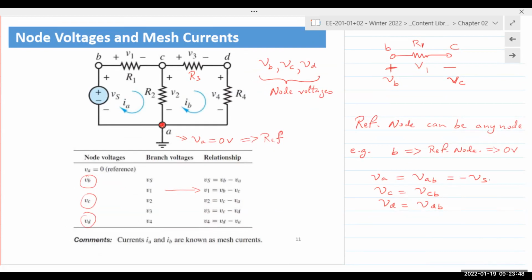So automatically, again, remember, we are solving for the voltages present at each node in the circuit, meaning those are the unknown variables, right? So if we choose one end of the voltage source as the reference, we automatically eliminate one variable from our analysis. So we only have to analyze for two variables, VC and VD. And so, again, we'll talk about this when we actually get to node voltage analysis.